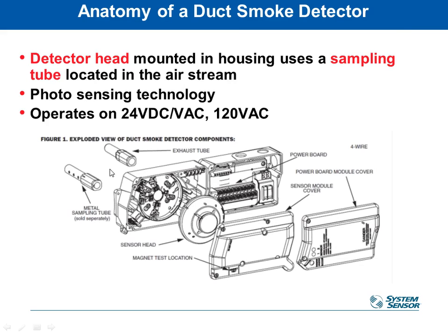So these supply and exhaust tubes, even though we call them supply and exhaust, that doesn't mean they have anything to do with the supply ductwork or the exhaust ductwork. They are the supply and exhaust tubes associated with that sampling section. They both go in the same duct.